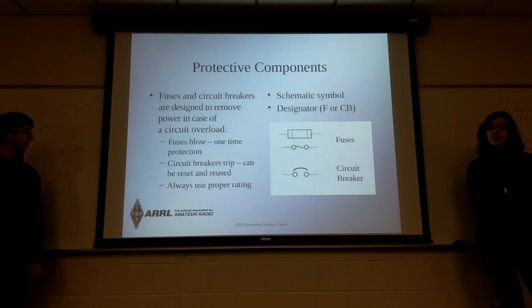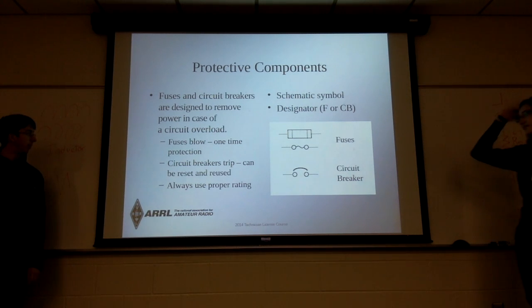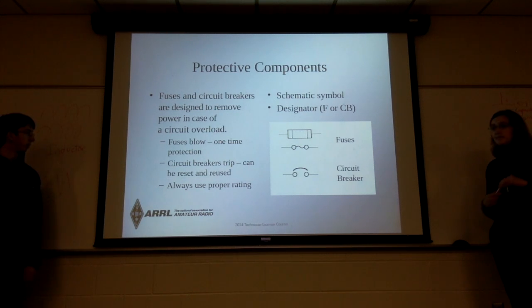But your car is still like this more than likely. Yes, most cars do not have breakers. Most cars have little tiny fuses. Little tiny plastic ones, yep. So circuit breakers, resettable; fuses, one-time protection.